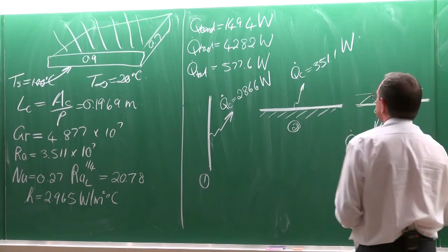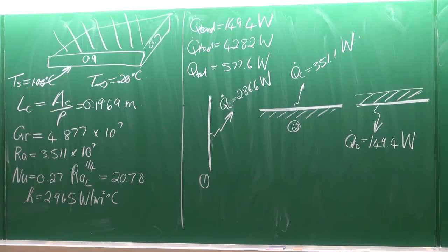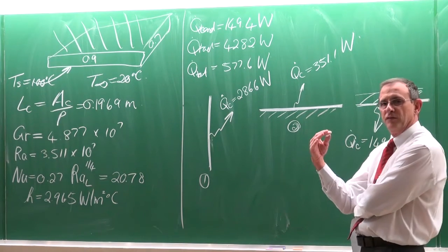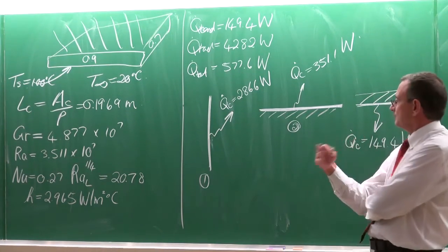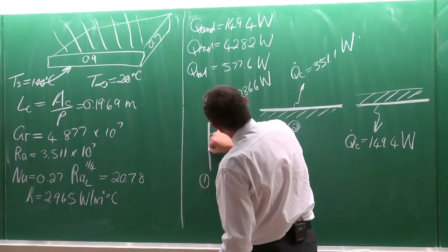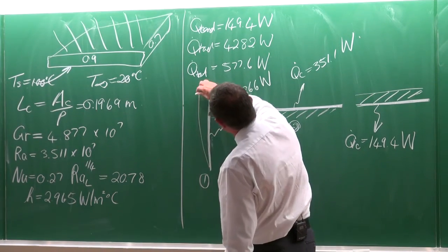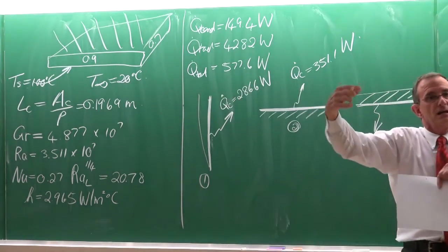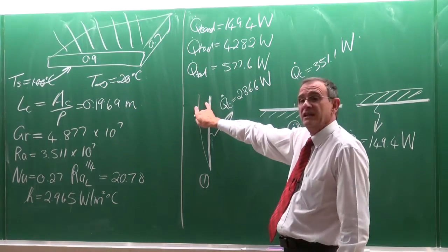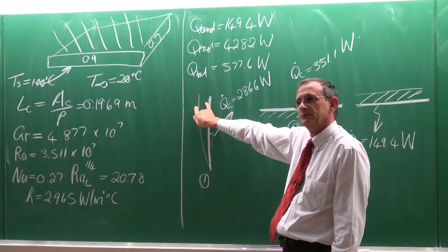The radiation for each one of them is the same, but it clearly illustrates the importance of the thermal boundary layer. This thermal boundary layer, as I explained at the beginning, is going to form like that, and it becomes thicker and thicker. And the thicker it becomes, the lower the heat transfer coefficient will be.